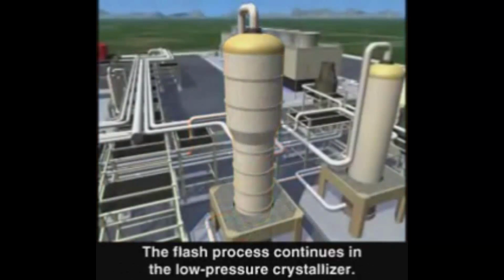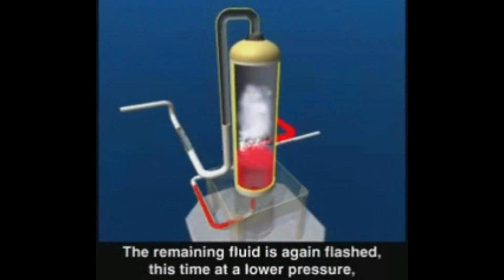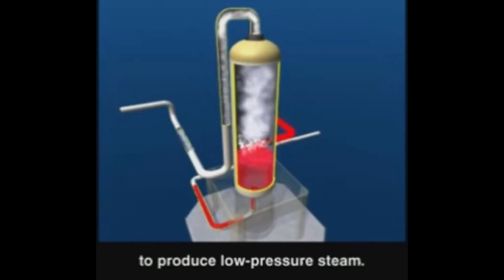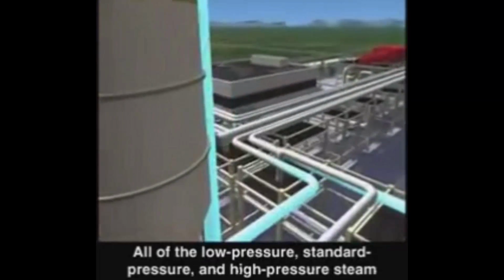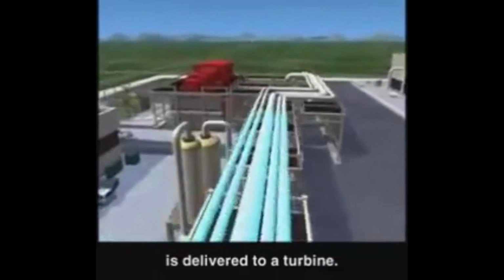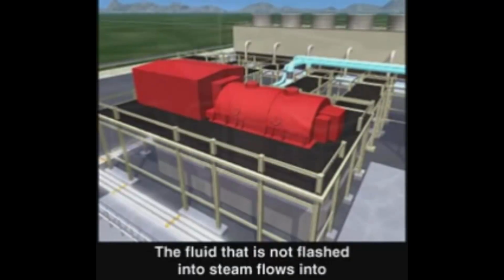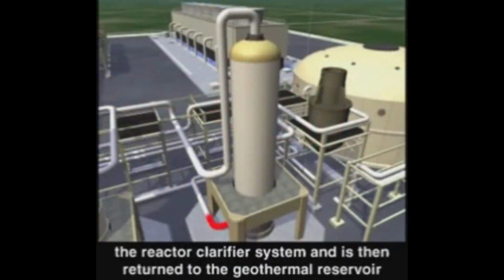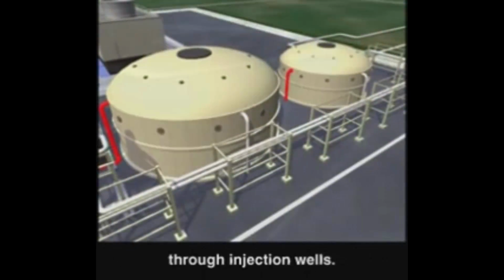The flash process continues in the low pressure crystallizer. The remaining fluid is again flashed, this time at a lower pressure to produce low pressure steam. All of the low pressure, standard pressure, and high pressure steam is delivered to a turbine. The fluid that is not flashed into steam flows into the reactor clarifier system and is then returned to the geothermal reservoir through injection wells.